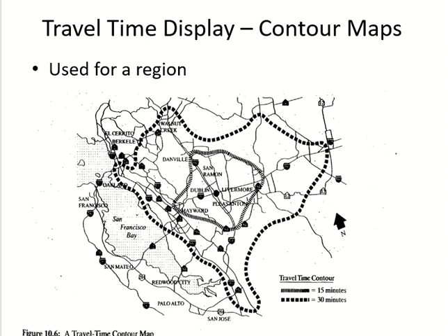And you have heard about contour maps in which course? Survey. Okay. So, like in a contour map, the lines show same elevation. In a surveying contour map, the lines show same elevation. In a travel time contour map, the lines show same travel time. Like surveying contour map, we need a benchmark, a reference point, a 0 point. Same thing here. So these lines are showing same travel time from the control point. This is my control point.